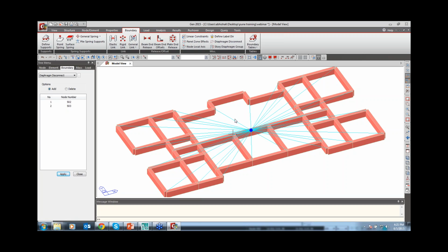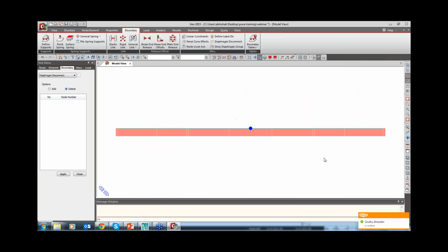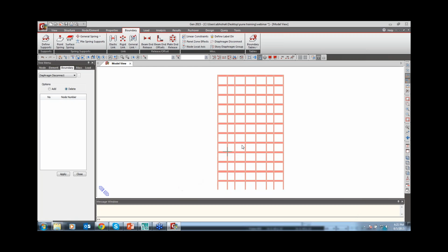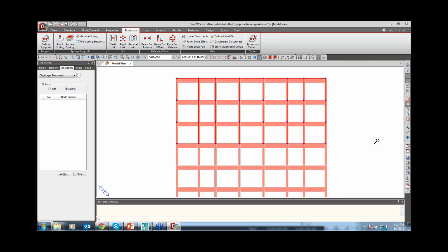Yeah. Now one more question asked by Vijay Khilari: how to change the floor to floor height after the building generation. Okay, so I will show you how to change the floor to floor height. Then I go ahead. I select this particular row. In the 3D form you have to select it. I just zoom in here and select in this way.